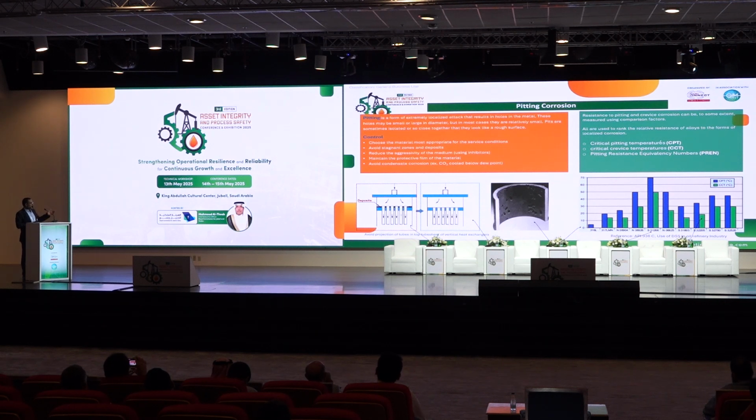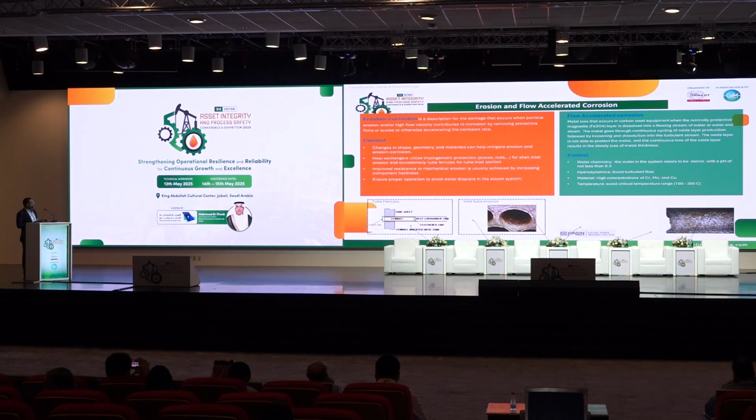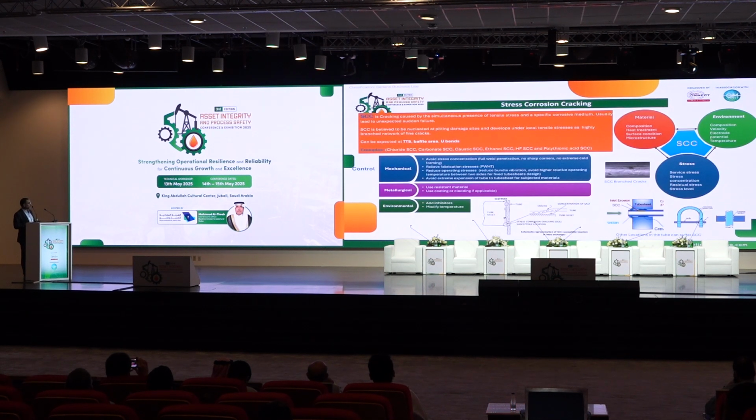And for pitting corrosion, as we said earlier, the attack can also come from the design itself, the design detail. If you are providing a location like the one in the bottom left, as you can see, where deposits can accumulate, you can have an issue of pitting attack. Same for erosion corrosion, or flow erosion and flow accelerated corrosion, which you need to think about not only from the material perspective, but also from the detail of the design to avoid such attacks in the tube, like what we can see from the ferrules inserted there.